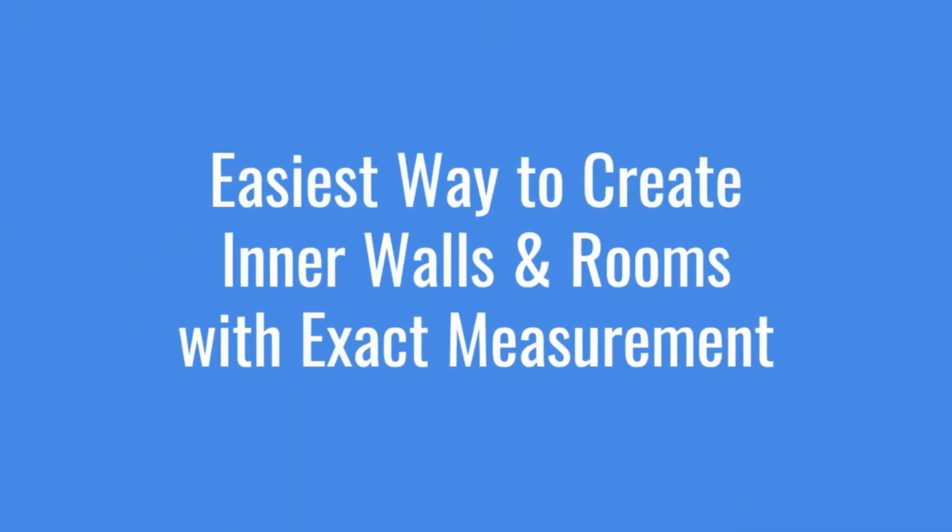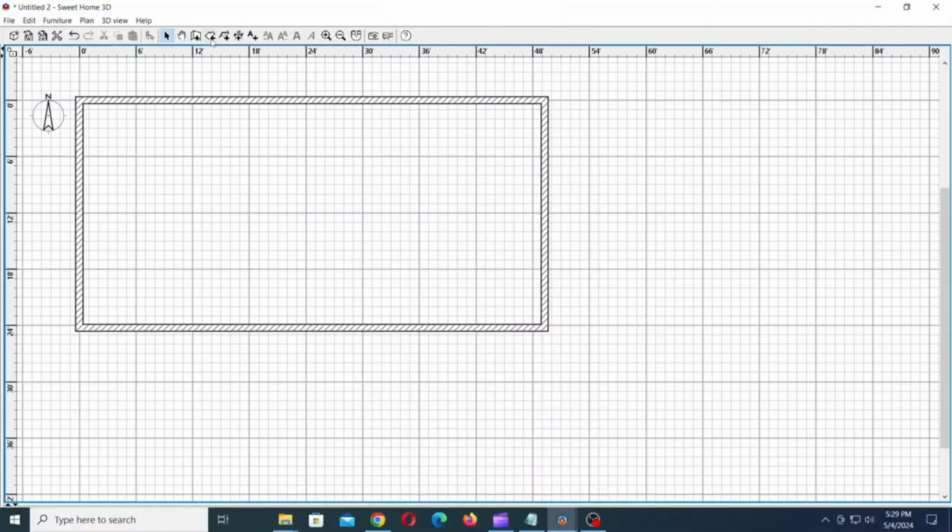Now I'll tell you the easiest way to create the inner walls. The easiest way is to first create rooms using the Create Rooms tool and then create the walls around it. To do that, just click on the Create Rooms tool. Move the mouse to one of the inside corners. Let's say the left top. As soon as you see a circle with blue crosshair, just click on that point.